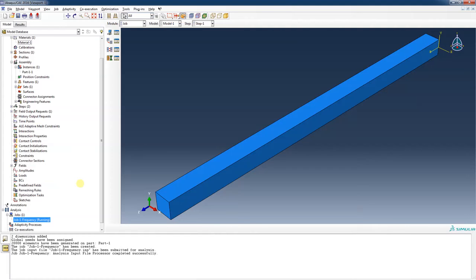When we calculate our modes using finite element analysis using these three-dimensional solid elements, the mode shapes that we will get will include the beam bending modes, but they will also have some torsional modes, and we'll see, since it's not constrained, some rigid body modes. So we'll talk about those. So the calculated mode natural frequencies that we get will be more than the natural frequencies that we have determined for the first, what did we say, 5 modes for our particular beam.